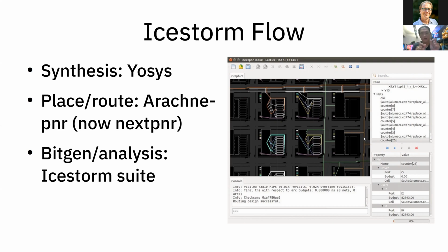And there's an empirical model you have to use to figure out what we are going to model that at. Because if you say, let's assume that all the switches are in the worst case corner, then you're going to be pathologically slow in your result, and it doesn't work. So there's an assumption built into these vendor tools that deals with that. I think it's really hard to pull out, and in some cases I've noticed some problems, but you just recompile it and it usually works the second time around.